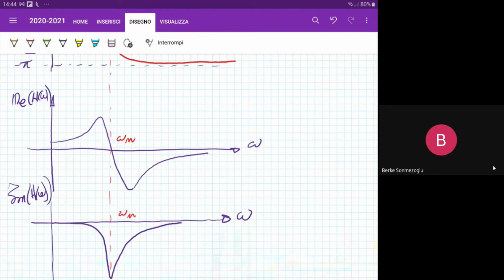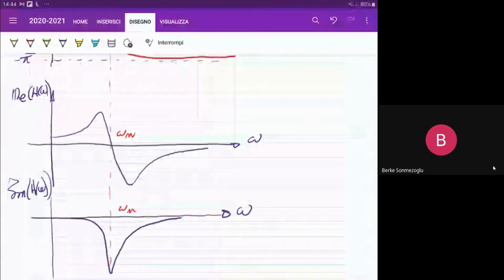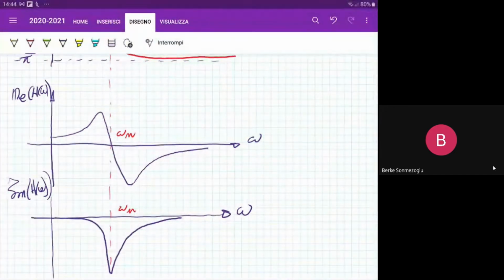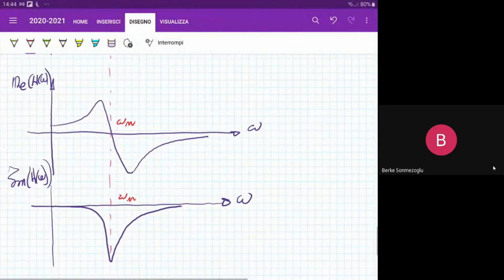And then when we are referring to the behavior of the frequency response function, when omega is going to infinity, very large values, then the response is always zero, both with respect to the real and the imaginary part, as we can see from this picture. And once again, the system is not capable at those high frequencies to follow the system input at those large frequencies.